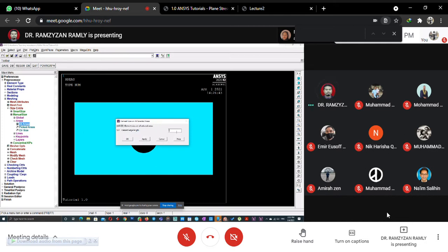Okay, and for this one, it depends. Okay, 25 is the distance, the mesh length. So we put whatever number that we want, between 1 to whatever number. If you put 100 or 200, your mesh will have only one unit. Then if it is small, your mesh will become small. Okay, let's put 20, say. Alright.